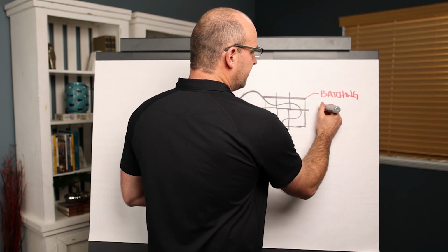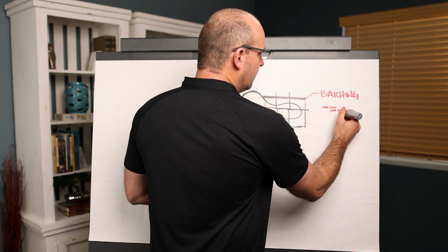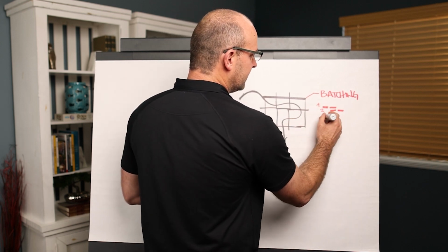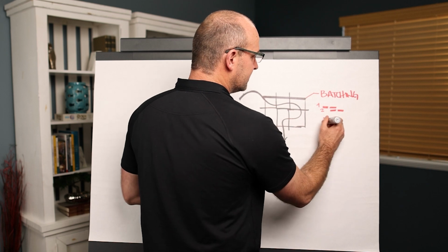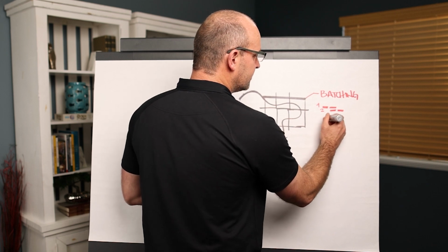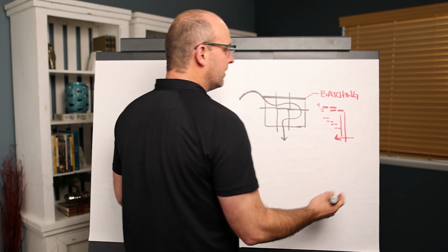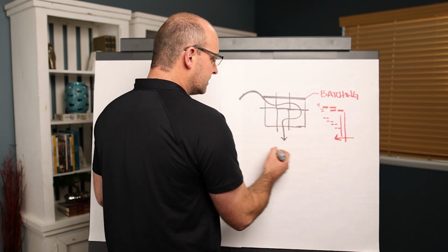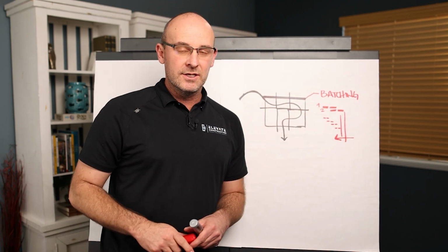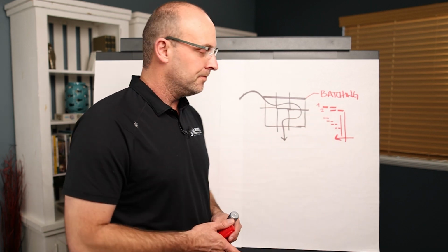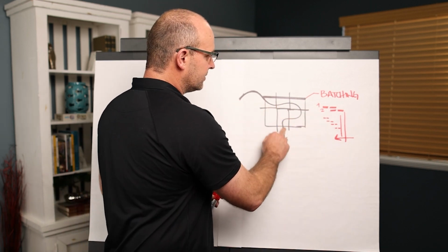Remember, when we are dealing with tact planning, we are able to take, let's say, a 2-zone scenario, and simply by, let's say, cutting the zone size in half, we are able to narrow how long that phase takes and gain time and bring that in. So if you select your work areas without the genius of tact planning and without doing a zoning analysis, you're wasting time. The path of construction is really nice.